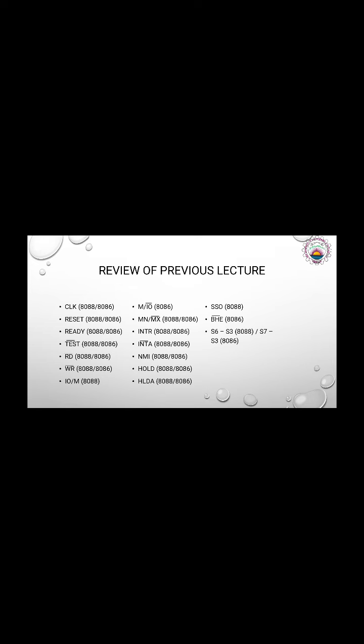In case of 8086, the M/IO bar pin will be having logic 1 when memory is accessed, and when microprocessor 8086 has to access IO, the M/IO bar pin will be having logic 0.